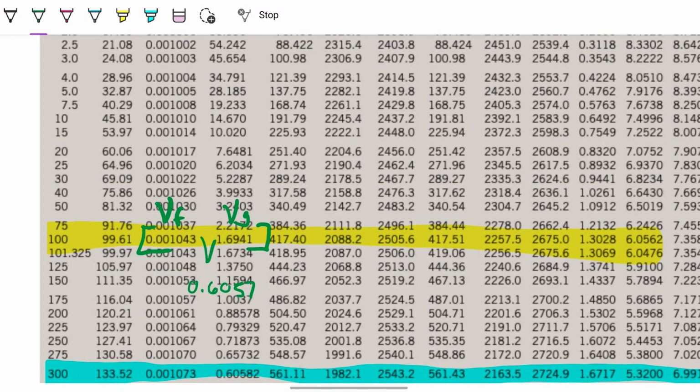And because it's a mixture, we can grab a lot of different things. The first thing we can note is that if it is a mixture, then we can be sure the temperature is 99.61, which is one of the questions. One of the things it's asking us is what is the temperature of the final state. So 99.61 is the answer.